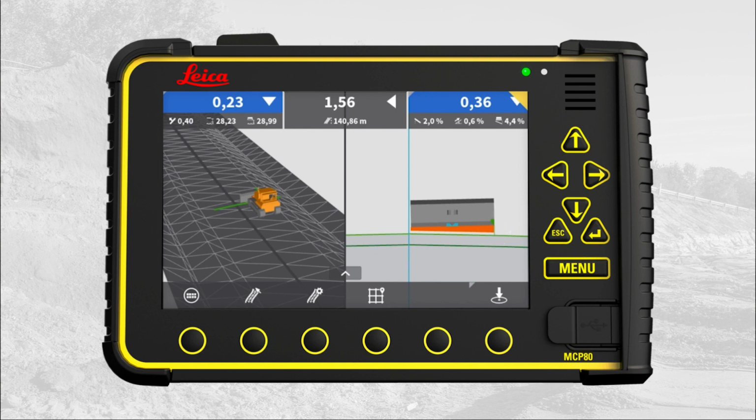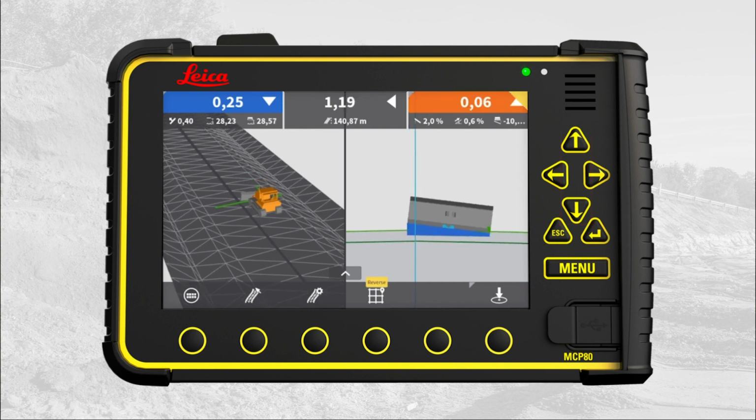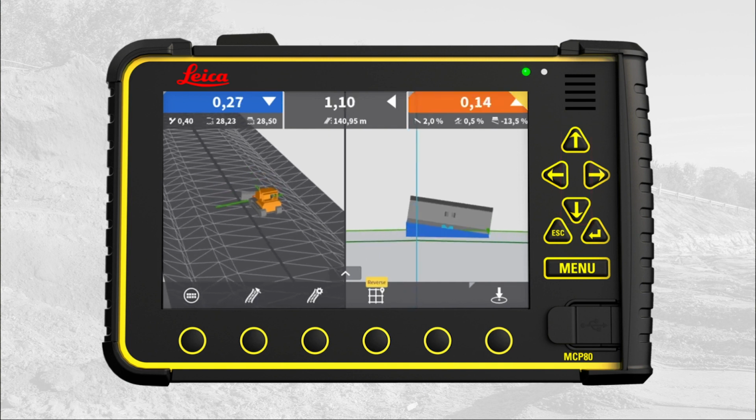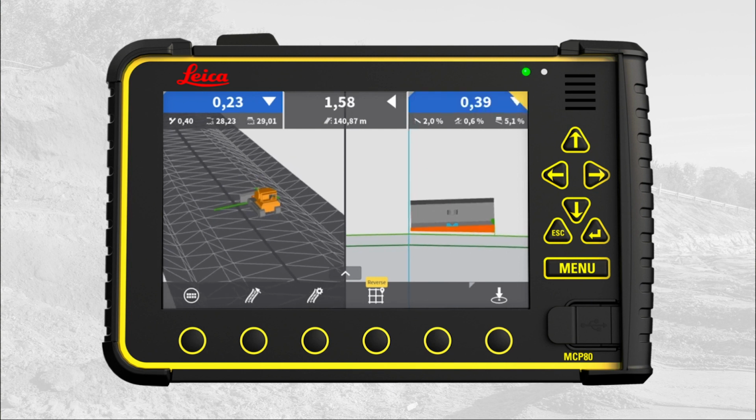We can change the height tool point location using the hard key arrows right and left. In this case, the side tool point is in the middle. We can change the side tool point location using the hard key arrows up and down. Below the cutting edge, you have a tilt indicator which will help you get the correct slope. You can turn this indicator off.